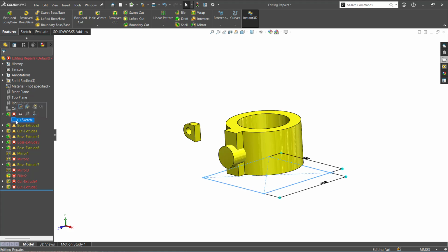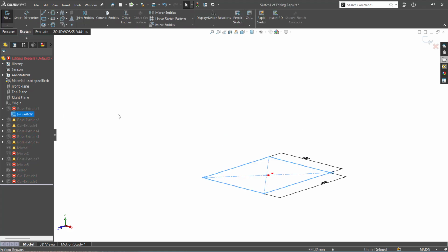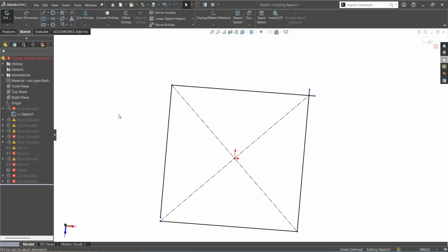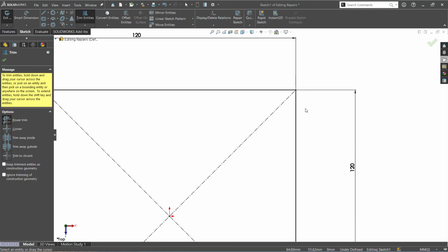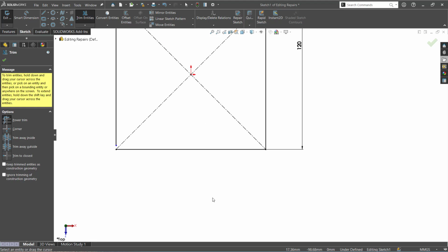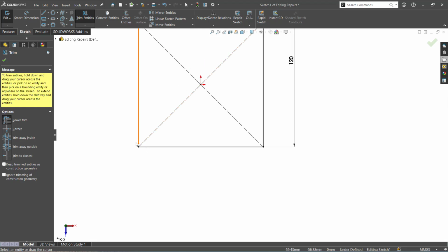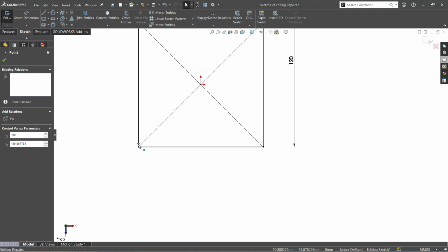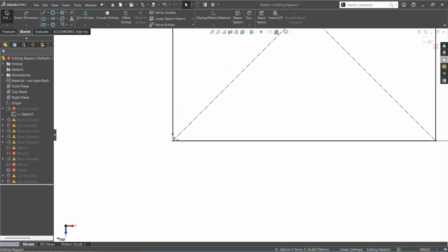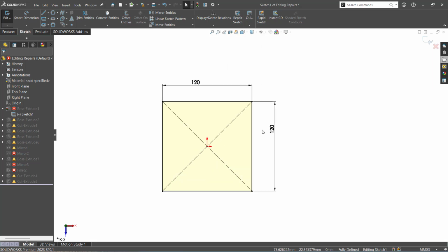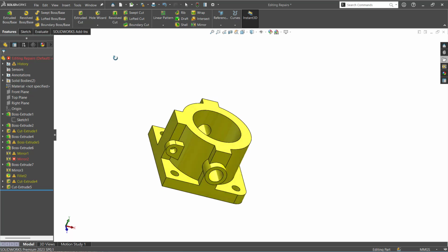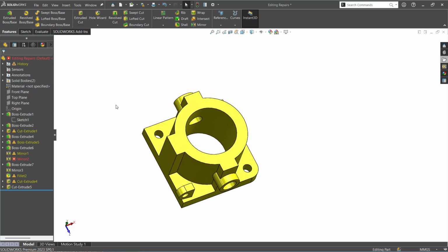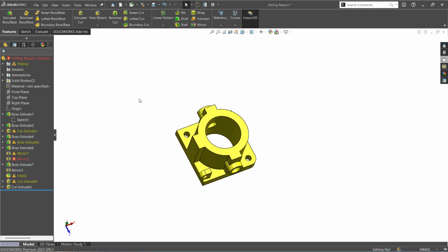First one is simple, so just double click on the sketch, make it normal. I could see there's an extension, use the trim, remove these two. And here it's open, so you can simply drag and drop it. Done, right? Exit the workbench, continue. Fine. Yes. Now what next?